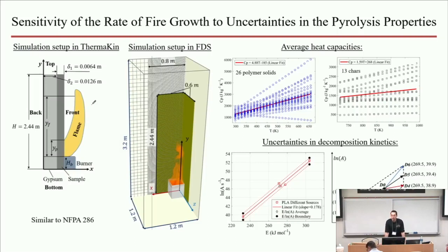So I think that in principle, the methodology, the framework of modeling, is the same. But how do you account for the non-thermally thin behavior of these fuels of complicated shapes? How do you measure it? How do you quantify it? That's a question that is not straightforward to answer, because you always want to do these experiments in such a way that the boundary conditions are perfectly controlled. Only then do you get insight into what's really going on inside, right? But when it's perfectly controlled, it means that you want nice flat surfaces and solid things, and that's how you can actually do it effectively.